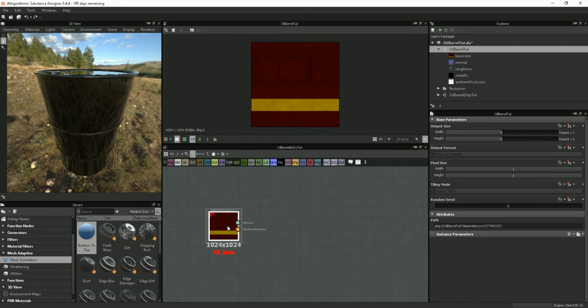If we want to see the outputs for this, we can just press 2, and this is going to show them. If I press 3, it goes between these two things. So it's showing our outputs and just showing a simplified version. One thing you may not have on as well is the information, this display connector name. If you don't have that clicked on, then it's not going to show you what these connections are. So that's quite useful to be able to go over here and see what these things are. So we have our material, we have our ambient occlusion outputs there.